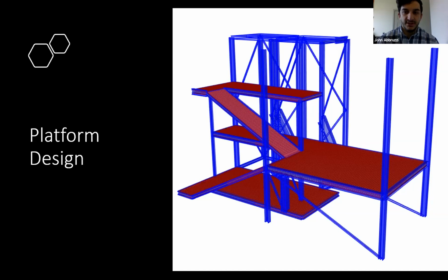We have chosen to use steel W sections for the beams and columns and HSS sections for the lateral bracing. Using SAP's steel design function, we were then able to determine whether the sections we chose were suitable. We started with W4 beams and columns and small HSS sections for the lateral bracing and ran individual analysis on each beam until the structure was safe. We then collected a range of safe steel sections for beams, columns, and lateral bracing.